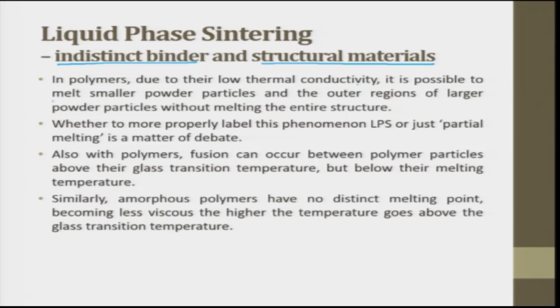Smaller powder particles and the outer region of the larger powder particles melting without melting the entire structure is nothing but distinct binder and structural material. Whether to more properly label this phenomenon as LPS or just partial melting is a matter of debate.